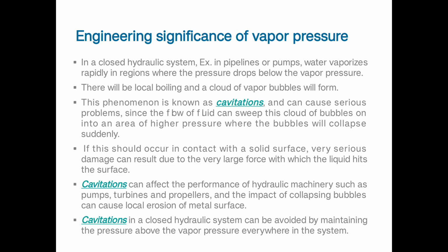That's what you can see in point 3. So if this occurs continuously, it will cause damage to every portion or the internal parts of a hydraulic system, say a pump impeller or a turbine propeller. Usually such cavitation can affect the complete performance of any hydraulic machinery.